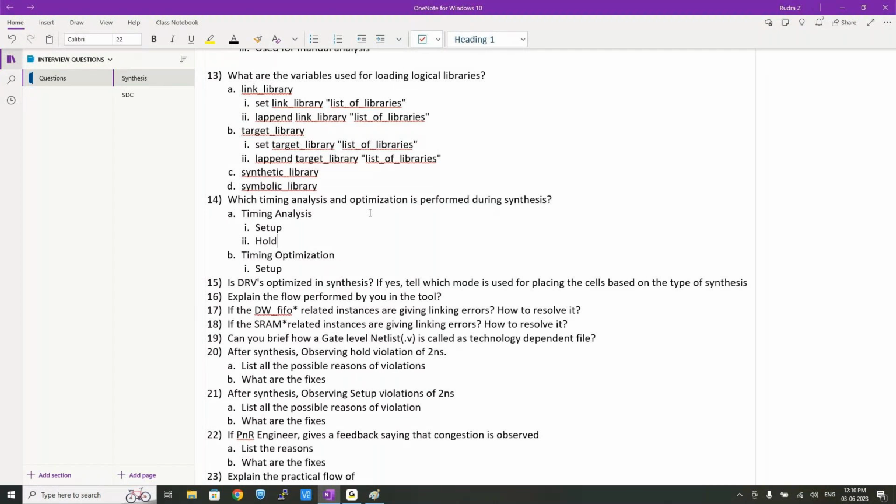So for example, there will be some cases where clock gating checks, we can say. There will be some timing paths to that particular clock gating. Okay, combinational cells. So in that particular combinational cell's endpoint, do you want to analyze it for hold or not? That comes from the architecture. That comes from the architectural information, whether you want to check it or not.